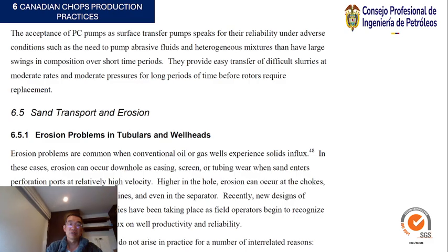6.5 Sand transport and erosion. Erosion problems in tubulars and wellheads. Erosion problems are common when conventional oil or gas wells experience solid influx. In these cases, erosion can occur downhole at the casing, screen, or tubing where sand enters perforation ports at a relatively high velocity.